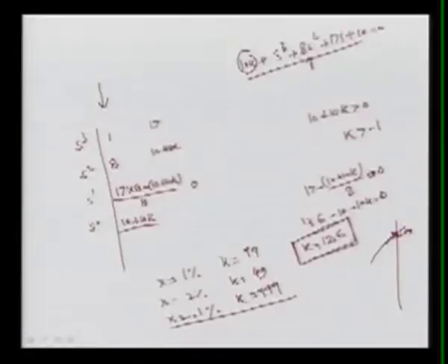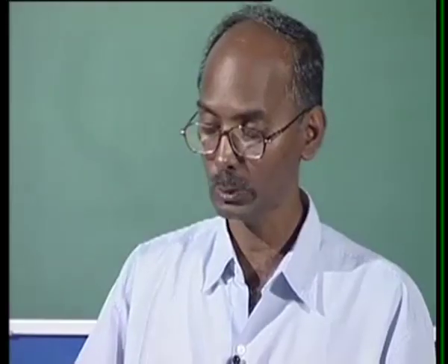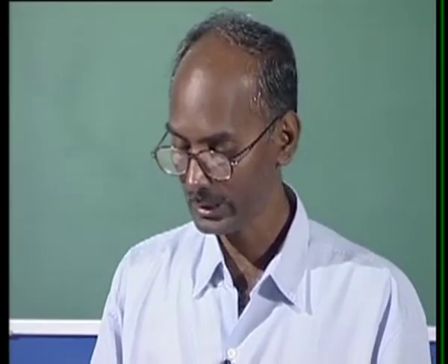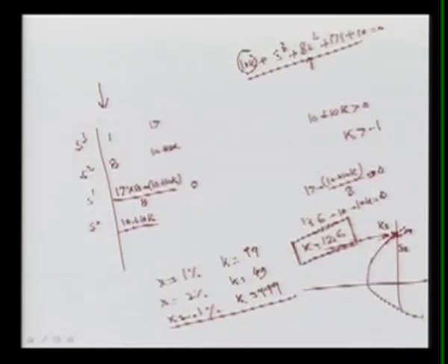Again, now we can also determine what will be the pole or root and where it will be. Here I obtained the k value, which we calculated. Now I want to know what will be the s value, what will be the root, what will be the magnitude where it is crossing. We had this characteristic, if you remember, one branch crossing here, moving like this and going like this. So I want to know this value of s here, and that can be obtained by the auxiliary function.